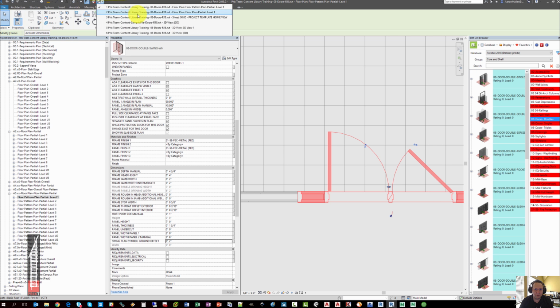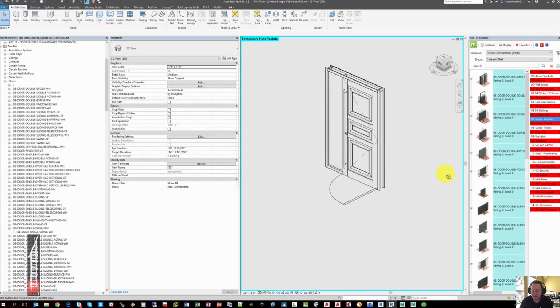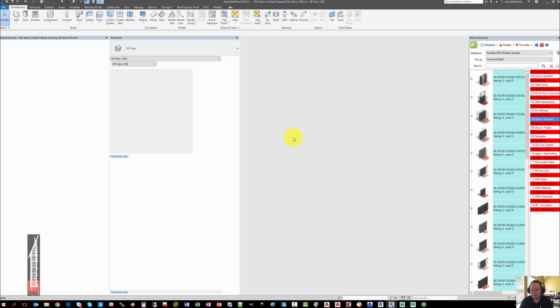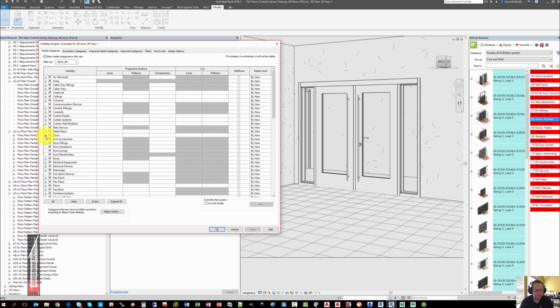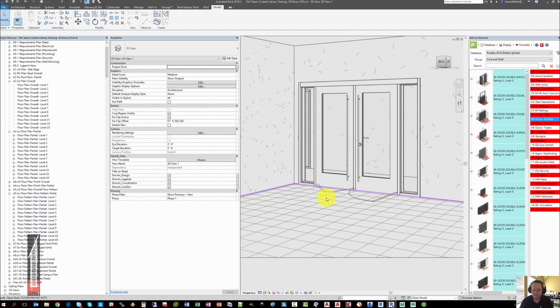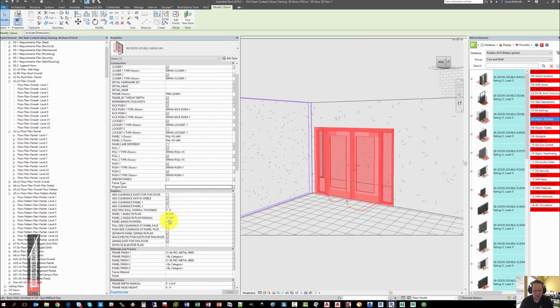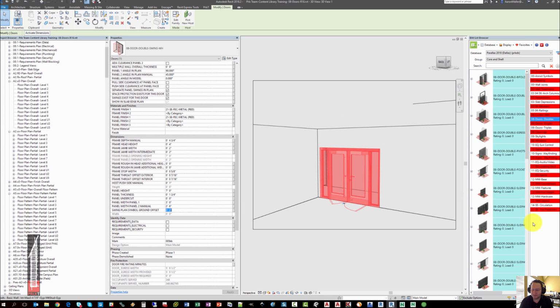So if you are in your perspective or 3D views and you happen to notice that the lines themselves are above the door, that would be why. You'll see them here. If you want to lower it, you can simply select the door and change the instance parameter. I keep them on 2 inches as that is generally higher than most finishes that get placed in architectural models.